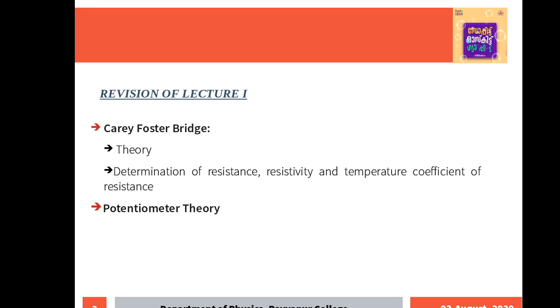In electrical measurement, basically, we measure 3 fundamental quantities like current, voltage and power. But the measurement of resistance is also very important in the case of design of electrical circuits. In order to measure the resistance, we can measure the fundamental quantities voltage and current, and dividing voltage by current gives the resistance.